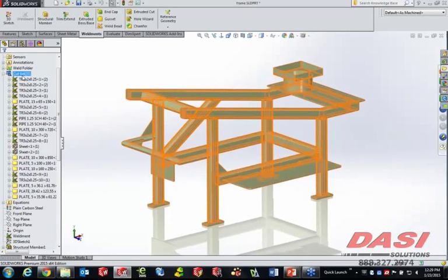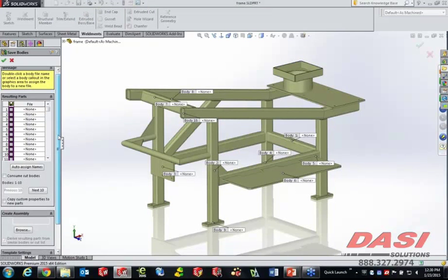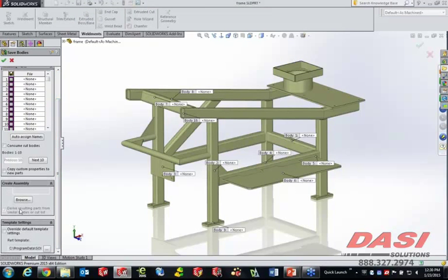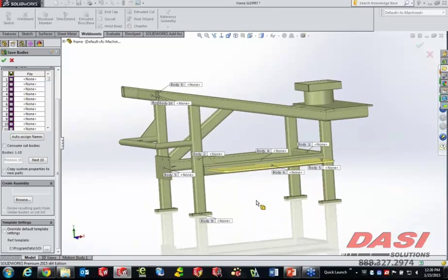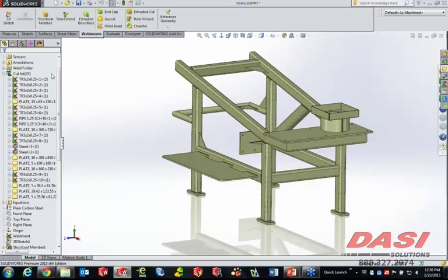You also can right-click and save this assembly. So if you do want to save this out as an assembly, you can click Save Bodies. And this new functionality actually allows us to go ahead and take multiple parts of the same size and create a single part file, quantity of 4 in the resulting assembly. Prior to that, every single body was exported as an individual part file, but now this derives resulting parts from similar bodies or cut lists. It will take any identical components, export them only one time, and then build an assembly with the proper quantity of those. So that's the most important part there. So lots of great things with weldments. Cut list interaction and on-screen interaction definitely top the list of those.